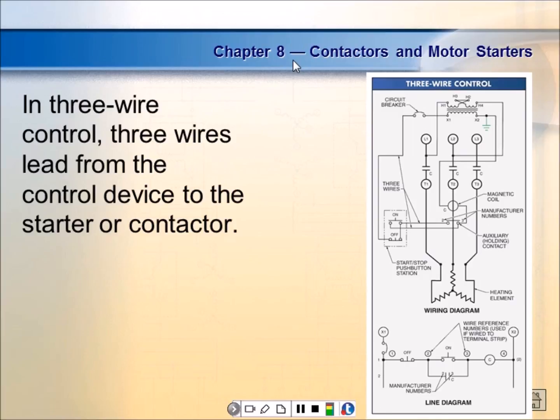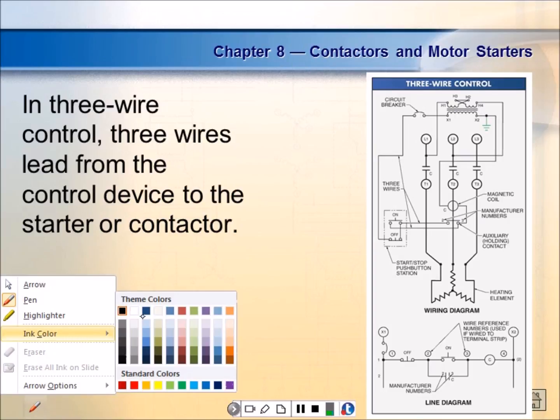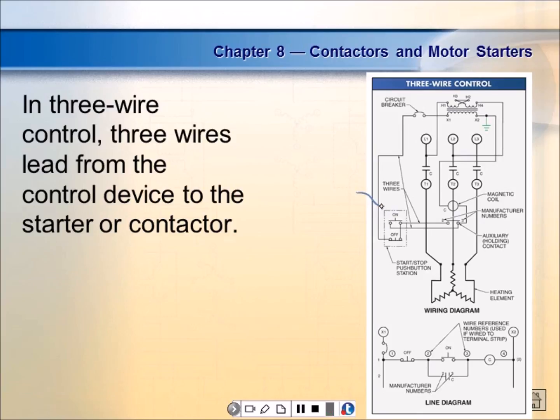So we have a wiring diagram here, and I know that these two push buttons are inside the same unit, right? Because they have that symbol that we talked about where we use long lines and dots and dashes, I guess you'd say. And then I know this relay is located somewhere out here pretty close to phase 2, right? And then these are the contacts being controlled by that relay. But if I try to figure this circuit out, it's pretty complicated. Y'all see that? When actually the logic circuit looks like this.